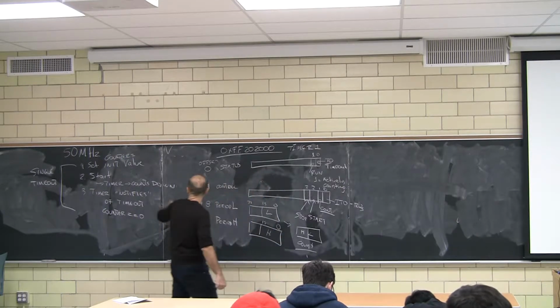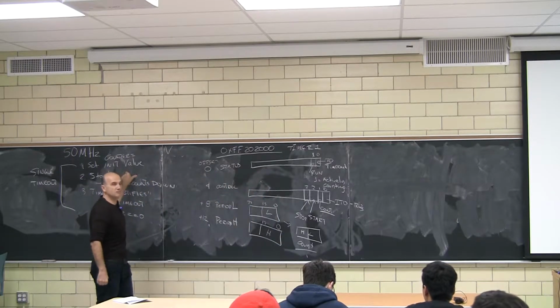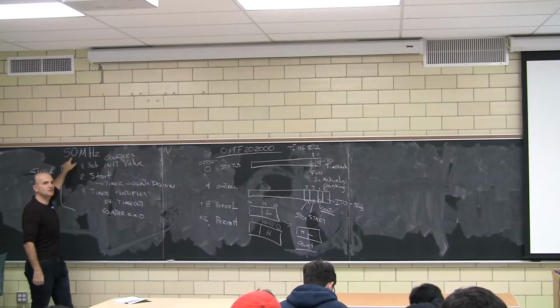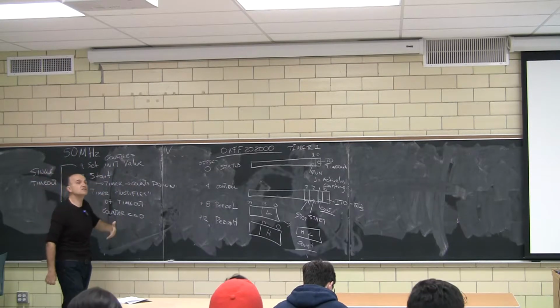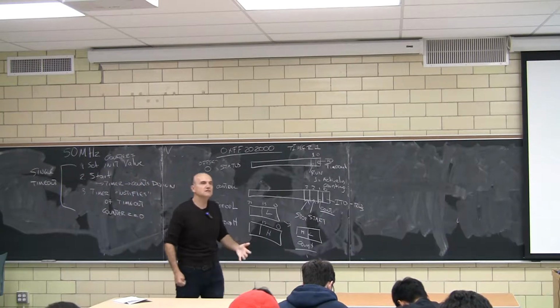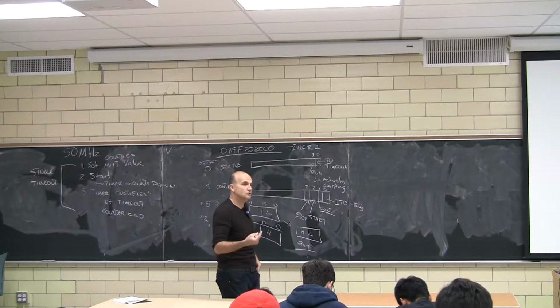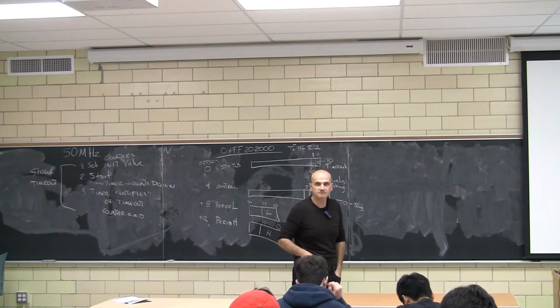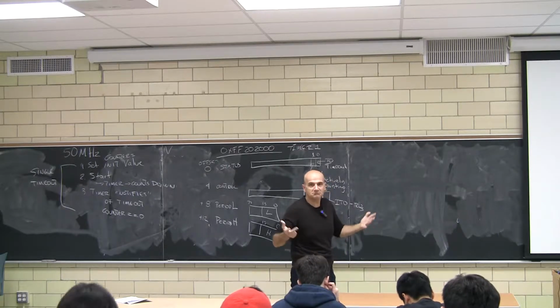And you're counting down from that at a rate that is 50 megahertz. So there are going to be 50 million ticks per second. You give me a value. If that number, for example, happens to be 50 million, then you're going to be counting for 1 second. If it's 100 million, 2 seconds. Fair enough? That's what it is. Ta-da.